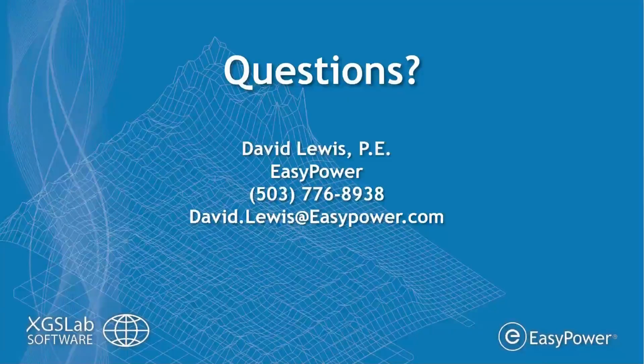And there are codes and limits for some equipment, and that comes from really the ability of that equipment's insulation to withstand the voltage potential difference that might be on a cable sheath. So there's not necessarily a GPR limit for a site, but there are limits for personal safety, and there are limits for equipment.